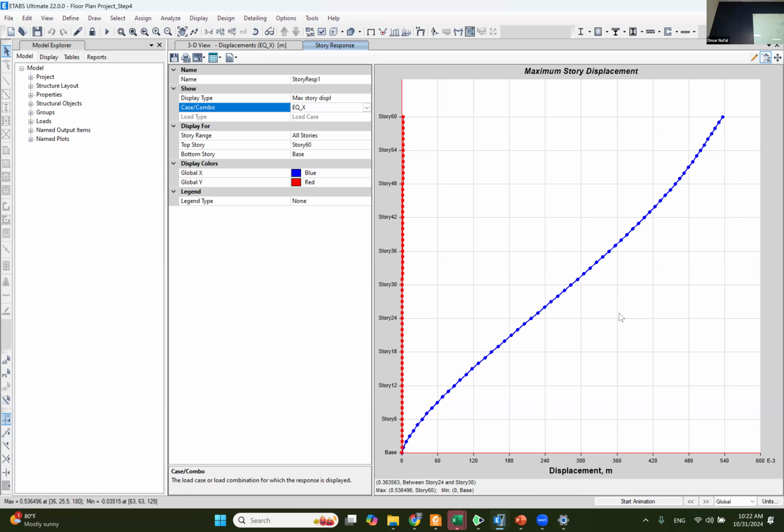If I crack the section, is this number going to get bigger or less? Bigger, right? Because the structure is going to be weaker, we're reducing the whole stiffness. So this will maybe reach 1 meter. That means I need to add more things. Let's say if you get your displacement like 2 meters, don't panic. That's trial and error; we are just doing a preliminary analysis. We're not going to allow this, but if it's 2 meters, we can go with it from an analysis perspective. But if we're going to build a structure, we can't let it move 2 meters.